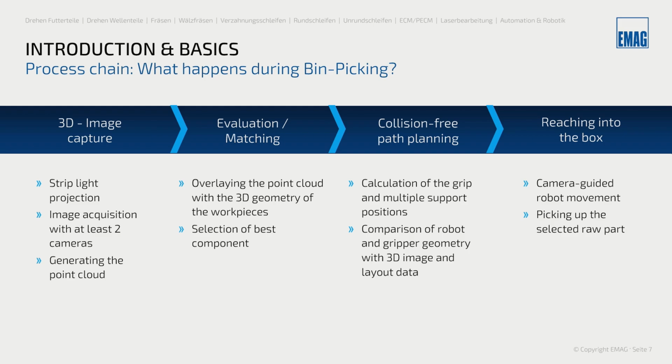With that done, we can go into the evaluation and the matching process, where we overlay the 3D geometry that we have of our workpieces with this generated point cloud, and the algorithm will check where it matches, and therefore we get information where parts are placed and in which orientation they are.